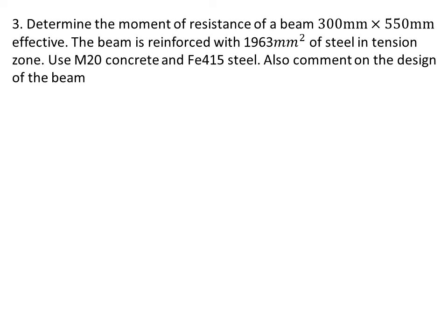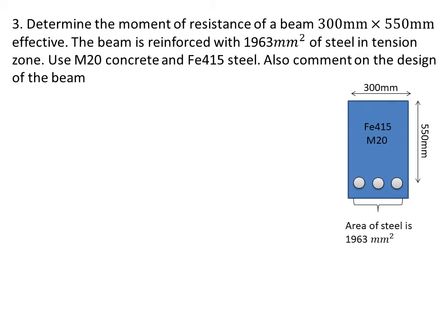Use M20 concrete and Fe415. Also comment on the design of the beam. We first write out the given details here: Fe415, M20, area of steel is 1963 mm square, 550 mm effective depth and 300 mm effective width.